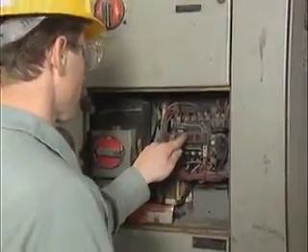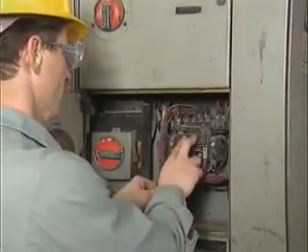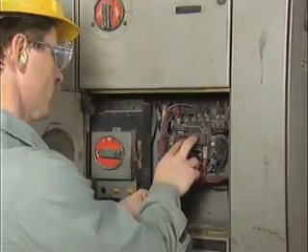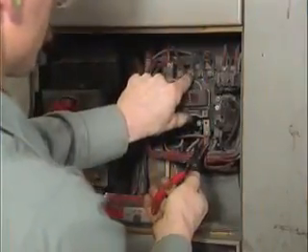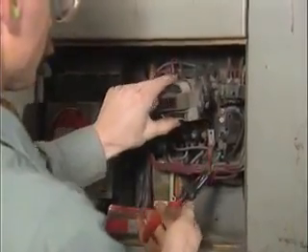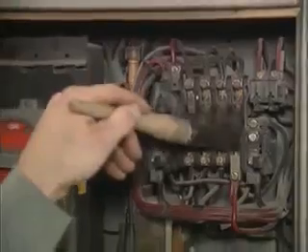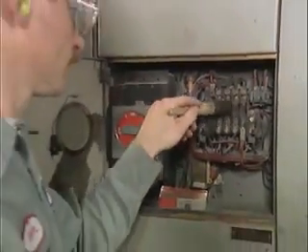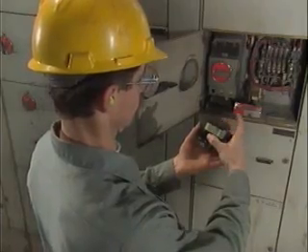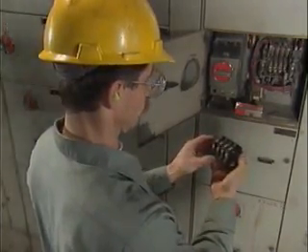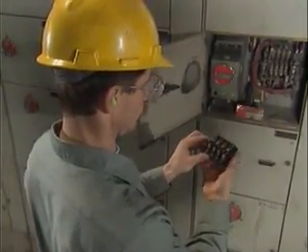When you inspect the controller's magnetic contactor, be sure to check it thoroughly for loose pins and screws and for broken parts. After you complete the visual inspection, remove the armature and movable contacts. Then clean both the stationary contacts and the movable contacts with a soft brush to remove dust and dirt. Then examine each movable contact and stationary contact to see if it is pitted or badly burned.